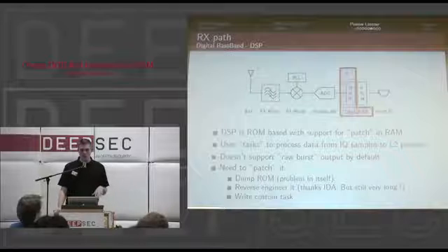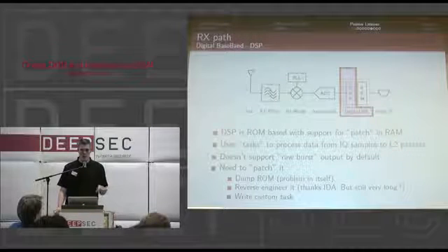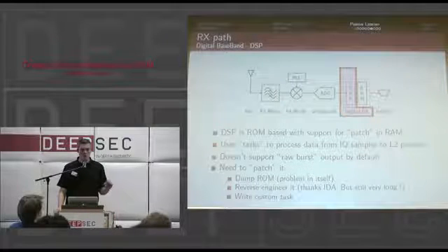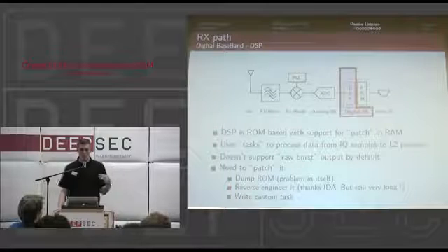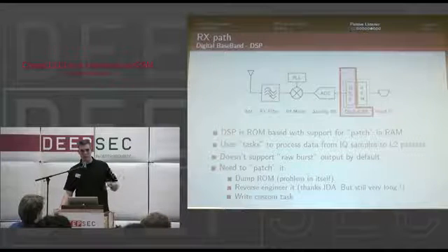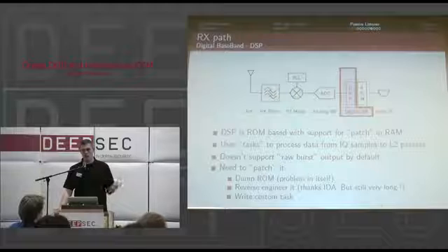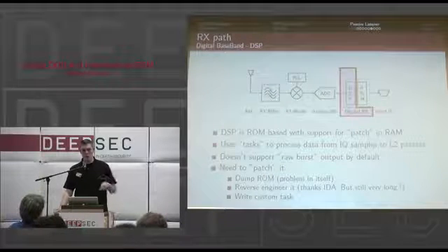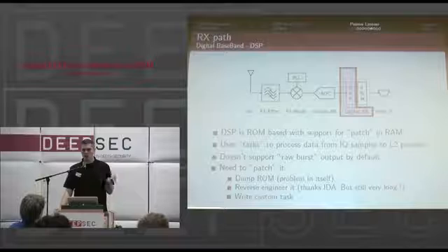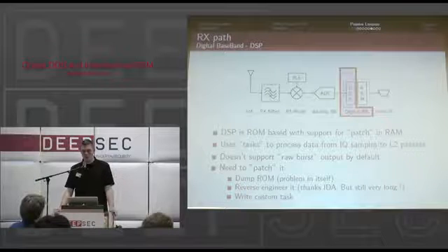What we can do, however, is apply small patches, because the manufacturer didn't want to reburn a new chip each time. So there is a small area of RAM where you can overwrite small parts of the installed ROM. They use function tables, and so you can overwrite entries in the function tables if you want to call your function instead of the default function.